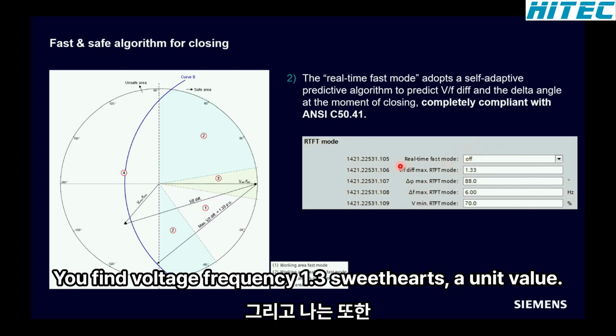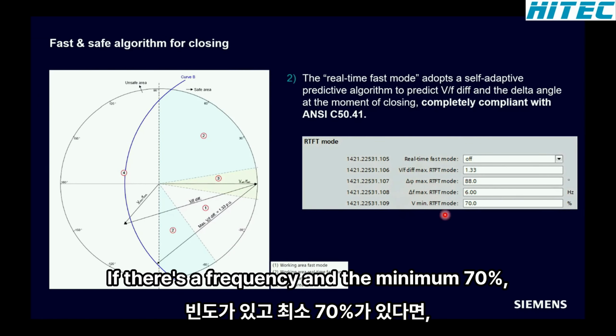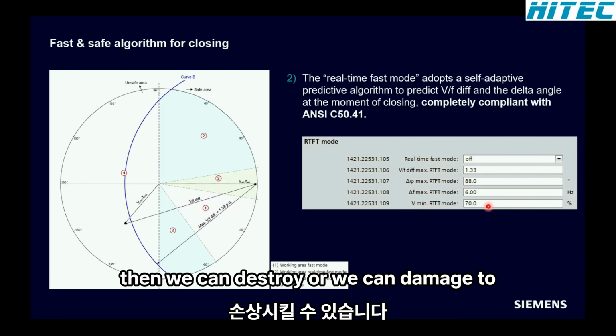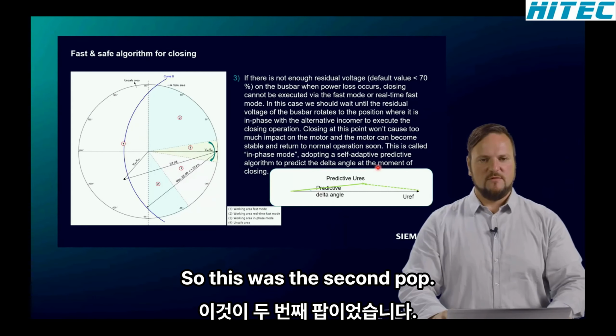Here you find the voltage, the voltage divided by frequency variation, the 1.33 Hertz or per unit value, and also the delta angle, the delta frequency, and the minimum voltage. And the minimum voltage is set to 70%. That means under 70%, it should not transfer in fast mode anymore, because if we are under this voltage level, then we can destroy or damage the equipment on the motor bus. So this was the second part.